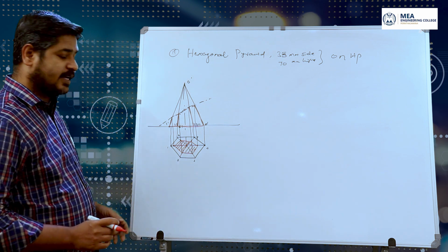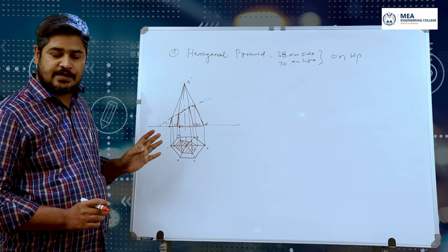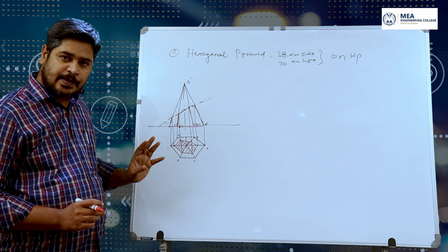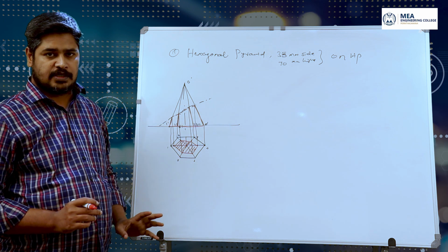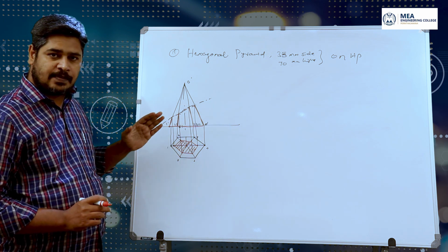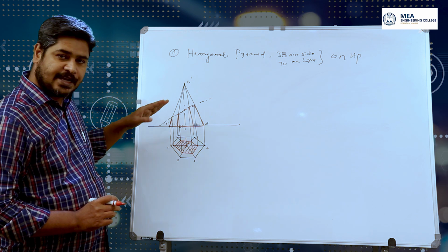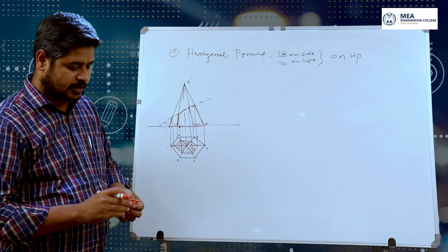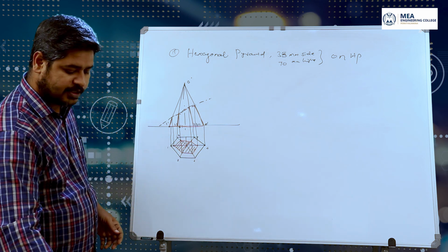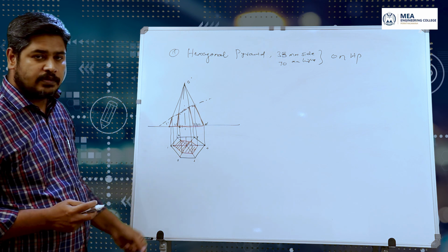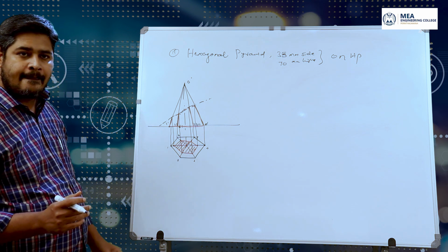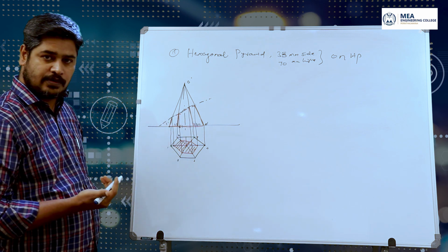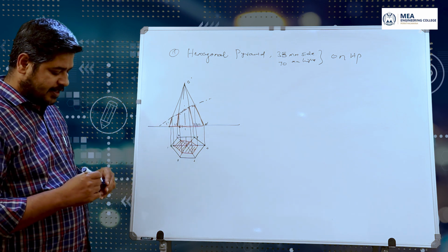Now our question is not construction of the sectional plane, or the sectional front view or true shape. Our ultimate purpose is construction of the isometric projection. If the solid is cut by some truncating surface, the remaining portion can be drawn with the help of isometric projection. Now I go to the projection. First draw the entire pyramid. You know how to construct it. For that we need the box.